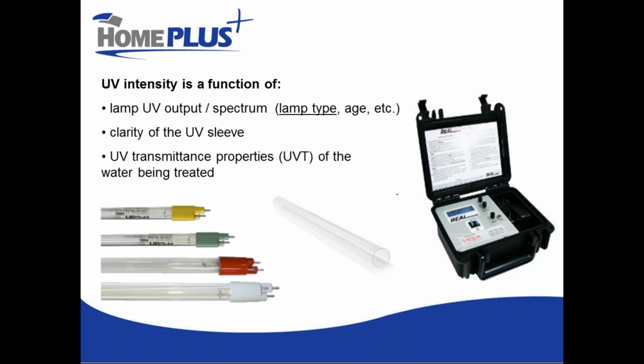However, it's possible to have water that is completely clear and still have organic matter in it that absorbs UV light. A good example of that would be if we were to dissolve sugar in water. Our UV transmittance would be very poor, but to our eyes, the water would look very, very clear. So you can't always rely on what the water looks like to know what its UV transmittance is. Certainly most water that is severely discolored will generally have poor UV transmittance.